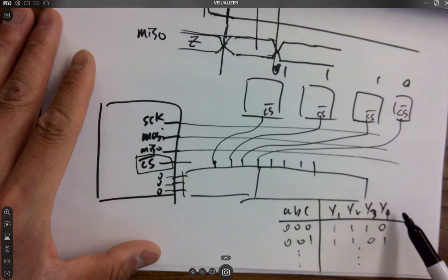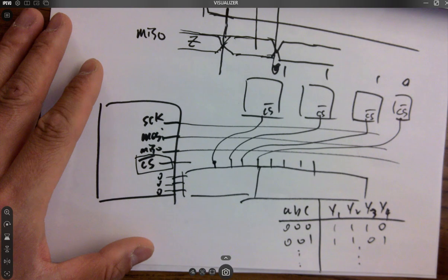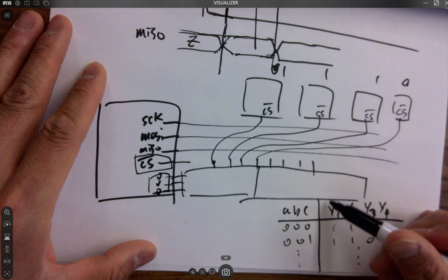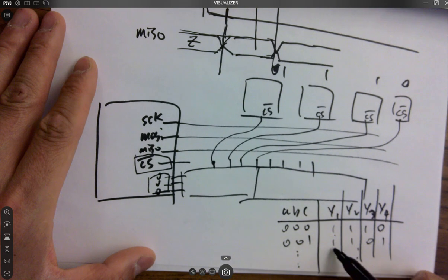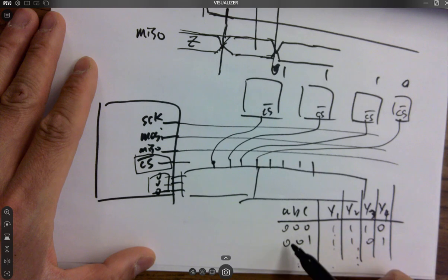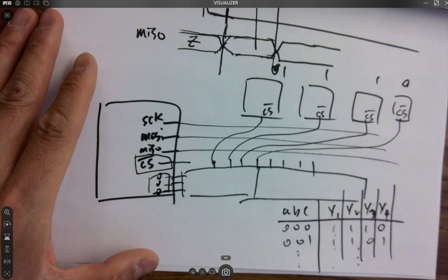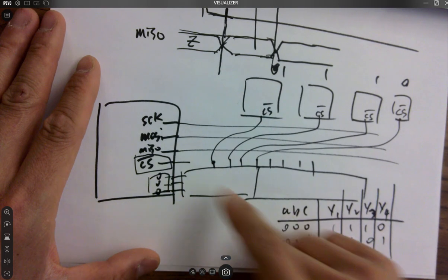So how many peripherals can you control by 3 bits? 8. And then we are looking at the little decoder circuit here. You could, by just looking at every single column, and then looking at all the ones available over here, and then form the min terms of the ABCs, right? You can design the combinational logic to control it.